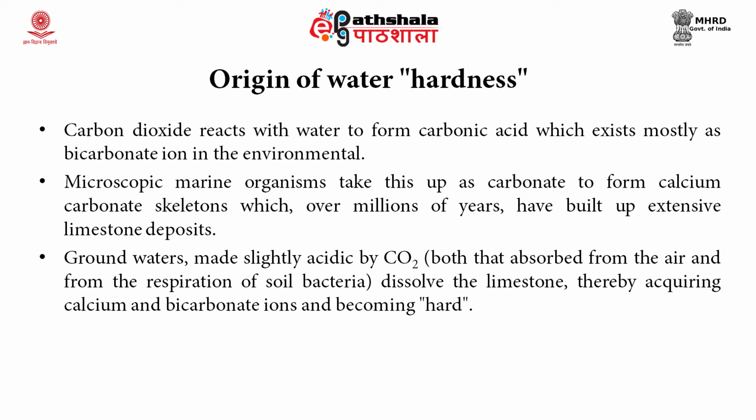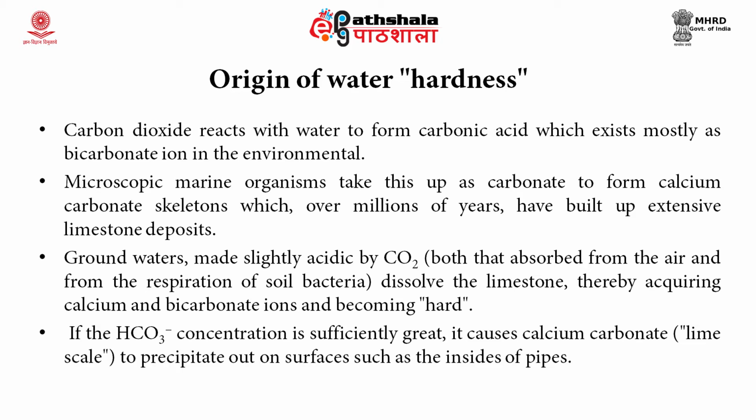The groundwater, which is slightly acidic due to carbon dioxide, dissolves this limestone, thereby acquiring the calcium and the bicarbonate ions, and becomes hard. If the bicarbonate concentration is sufficiently great, it causes calcium carbonate to precipitate out on the surface, such as the inside of the pipes.